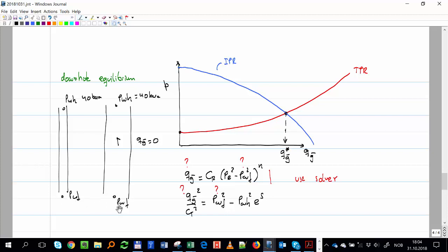How should the two pressures be? That's the point we're calculating here, right? We have fixed wellhead pressure, we have no flow, and we want to calculate the static bottom hole pressure. So are they different or the same? They're the same, right? You have no friction. You can make the conduit 1 kilometer diameter, you can make it 1/4 of an inch. So that point doesn't change.